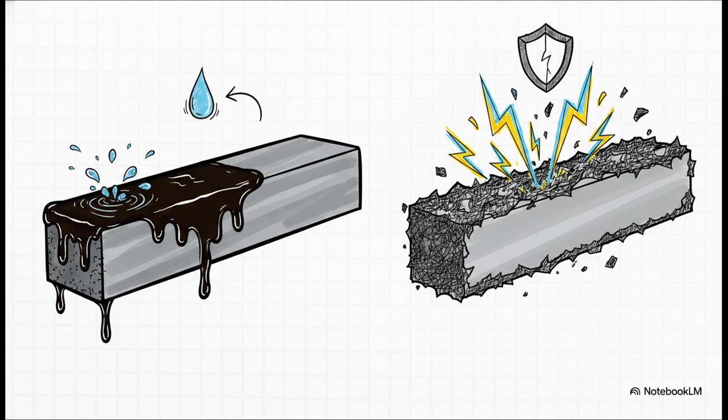So how do we stop these unwanted power loops? The simplest method is a barrier coating, just painting or oiling the metal so oxygen and moisture can't even reach it. But the most ingenious method is electrical protection, specifically galvanization. Here, we coat the iron with zinc. Because zinc has a higher oxidation potential than iron, it steps up and acts as a sacrificial anode. The environment will ruthlessly attack and oxidize the zinc instead of the iron, sacrificing the coating to completely protect the structural metal underneath. It's basically electrochemical self-defense.